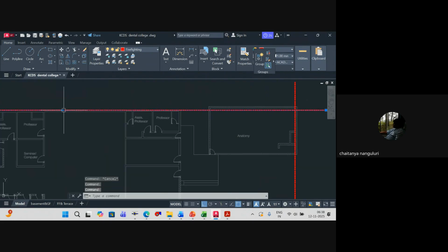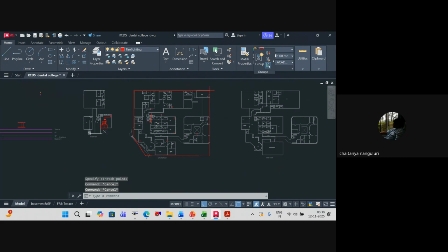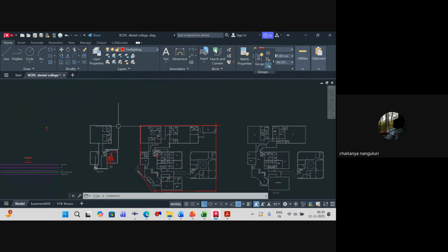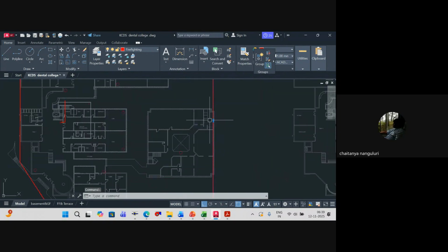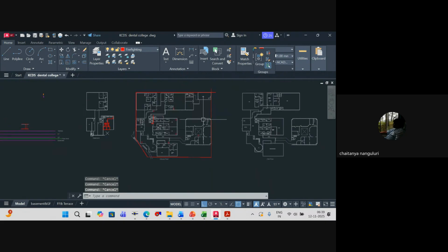As I've told you, you should have a gap of either 6 meters or 2 meters around the building. Minimum 2 meters, and you can have up to 12 or 15 meters. So in this case, let's say we have got a path all around. Shall we take around 2 meters distance, and then a fire drive of 6 meters? It depends on the architecture, you can't take it as such. So we'll take approximately a gap of some 2 meters.